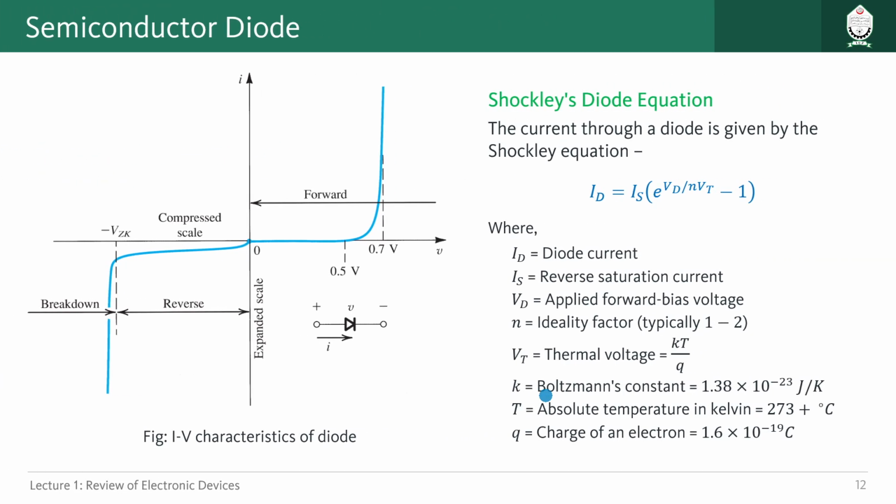So you see here we have seen for positive applied voltage or negative applied voltage how a diode behaves in terms of current, that is shown here. This particular graph is called IV characteristics, very important for our electrical engineering domain. Whenever we try to understand the characteristics of a device, we always look at the IV characteristics.